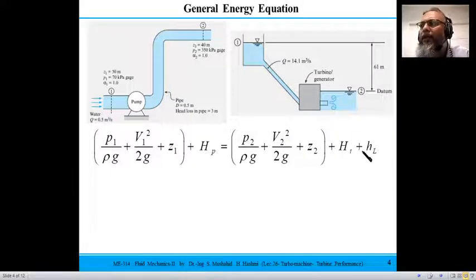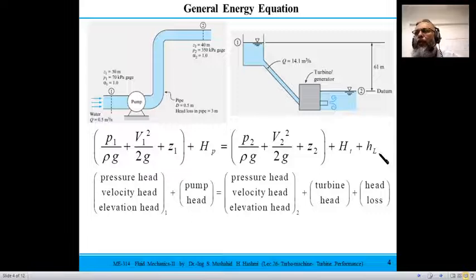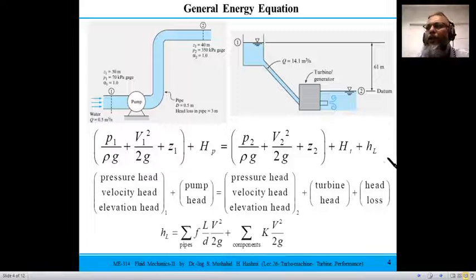And obviously whatever energy is going in is coming out, but you have certain losses, your hydraulic losses. And these head losses, we have already seen the formula for in a piping system. There is some pressure head loss due to friction, due to the small diameter of the pipe, and due to the flow rate requirement. And similarly, there are some minor loss factors, K factors. There are components involved like joints, valves and all these things, and there is some head loss.